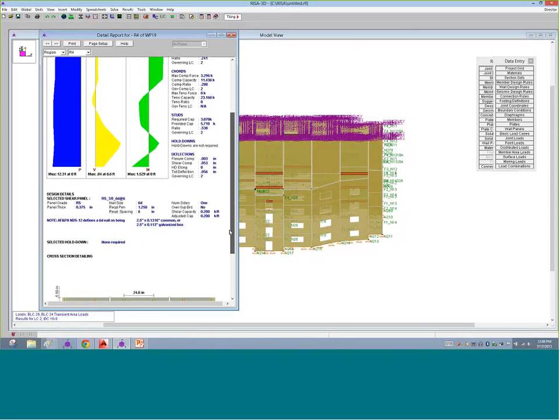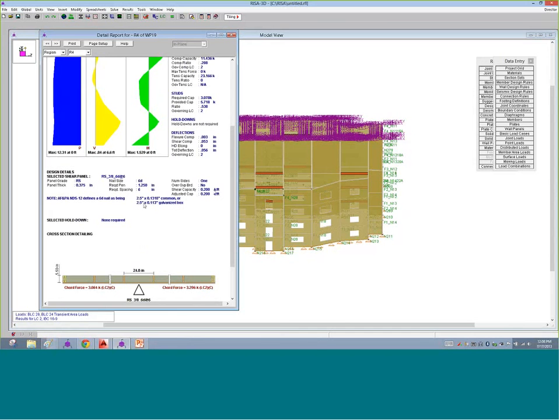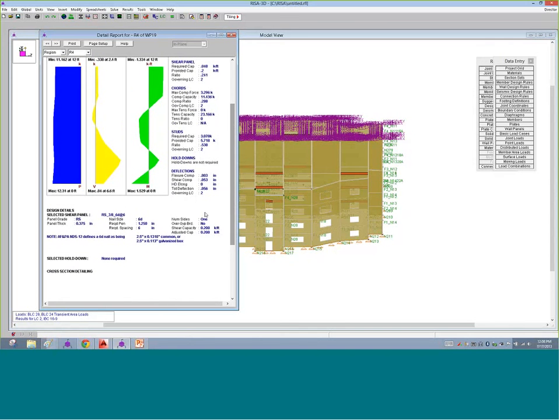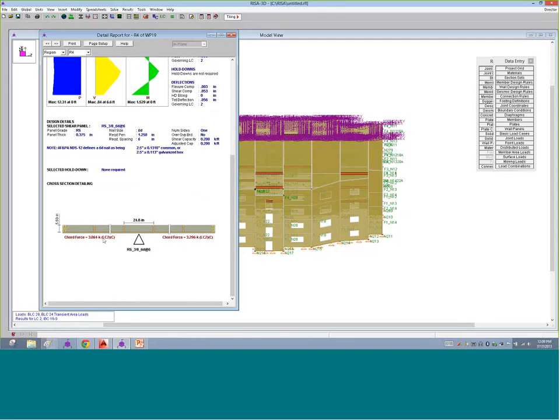So you see all that information, and we see the panel that was selected and the capacity of that panel and how that 0.02 capacity meets the requirement of what we actually need in this wall, which is a low loaded wall here, so we're not seeing much. But if we go below here, we see a nice schematic of it. We see what that panel is. It's a 3/8 inch panel. We see the chord forces where it's seeing compression on both sides here. So there really is no tension on this panel. That's why we're not requiring a hold down. It's heavy enough of a structure that this doesn't require a tension hold down. So you can see how that works, and you can see each side of that region and how that works in the segment.